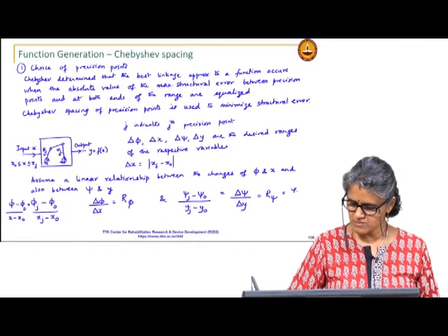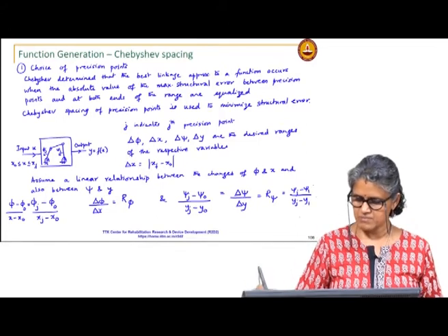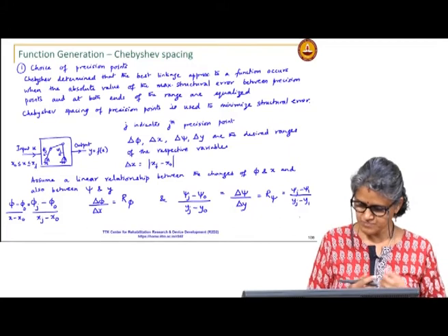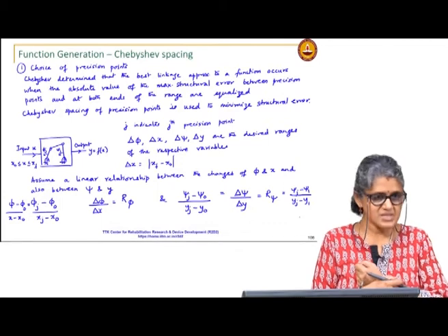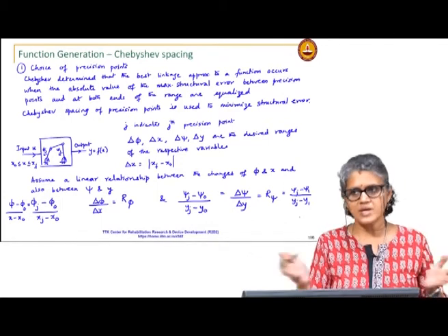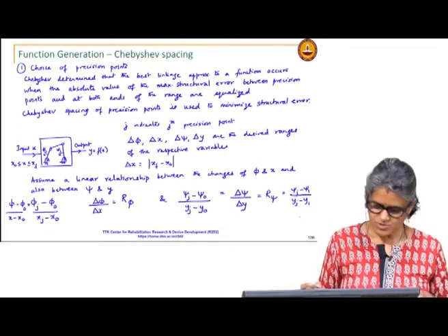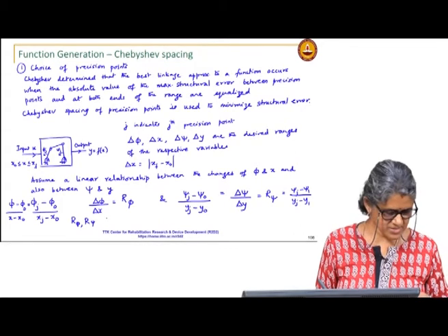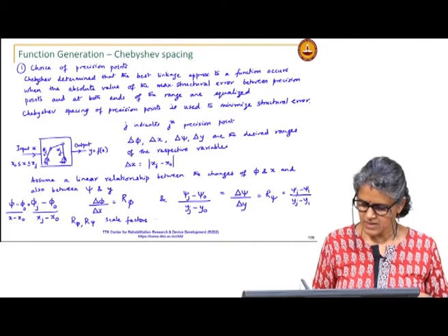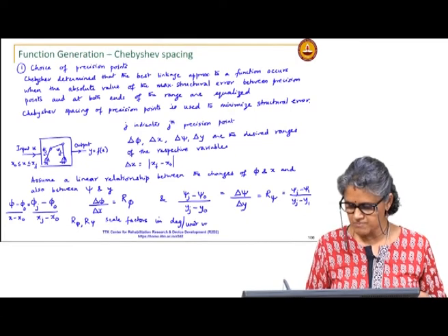Basically, you can do psi j minus psi 1 by yj minus y1 to determine the value, or use y naught or psi naught. It's a linear relationship, so any 2 points that you take give you the same result. So r phi and r psi are called the scale factors, in degree per unit variable.